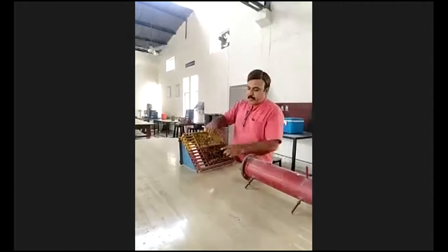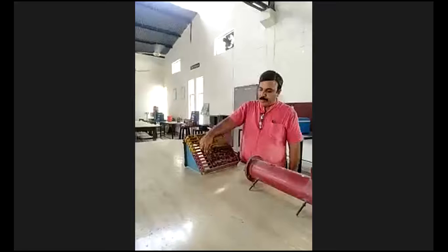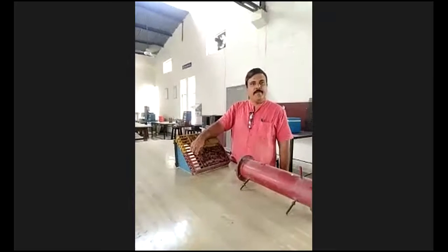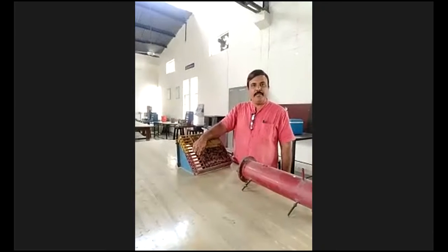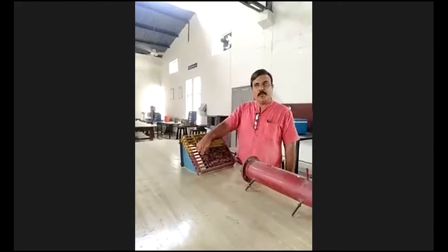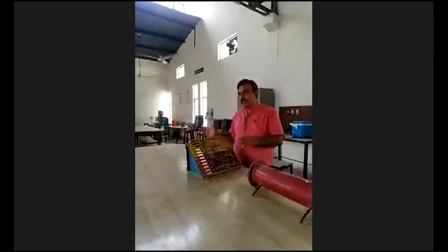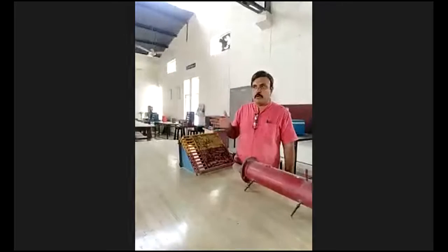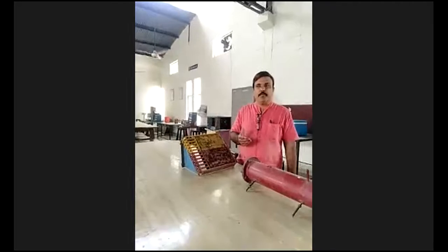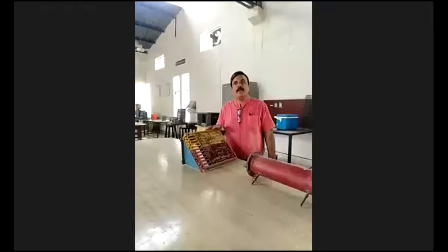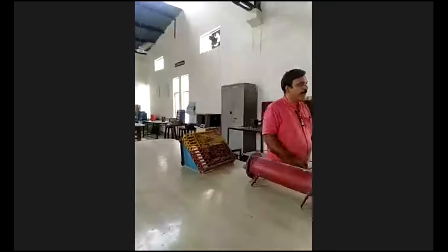The removal of heat also depends on the area of these fins. If the area of the fins is large, then more air will come into contact with them and more heat will be transferred to the surrounding. In our window type air conditioner, more air will be supplied over this pipe, so more heat goes to the surrounding. So the COP in such a case will be large as compared to the simple convection type condenser.